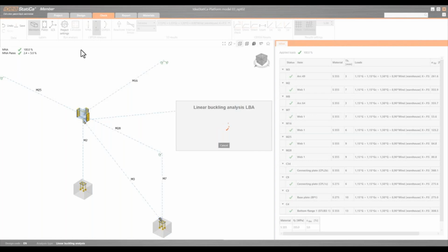Again, the buckling analysis is only an indication, and it is required because I want to identify the critical buckling shape, and you amplify it and use it as an imperfection for the GMNIA analysis, which is basically the only analysis that can account for all these effects in gusset plates. So let's wait a bit until the buckling analysis is over.